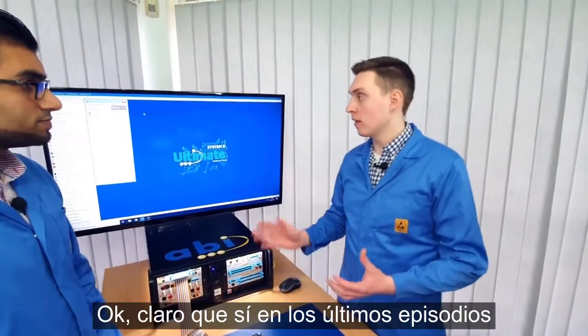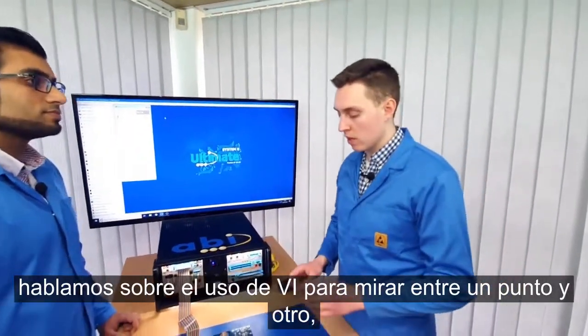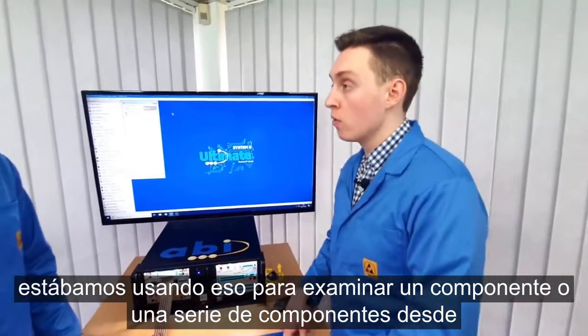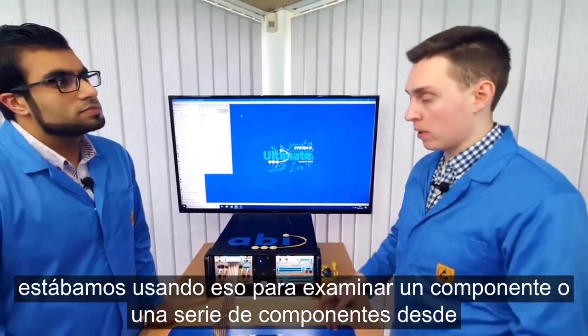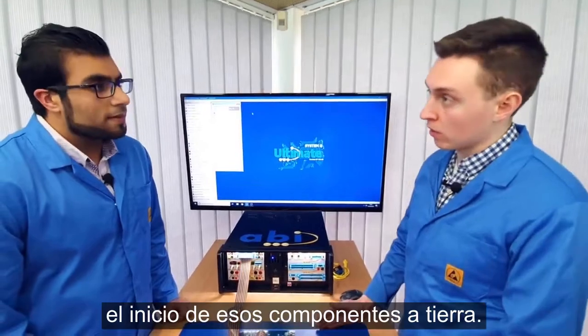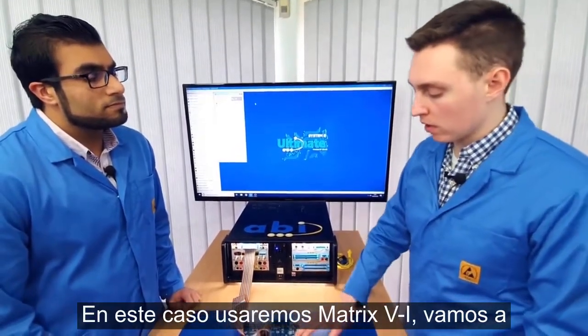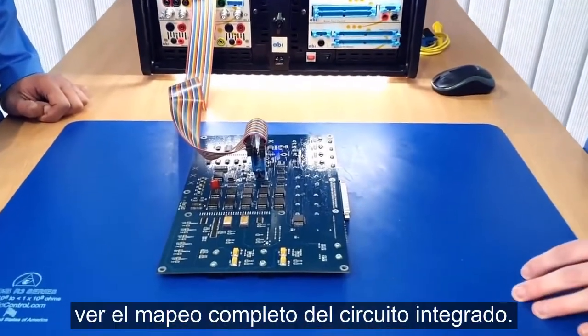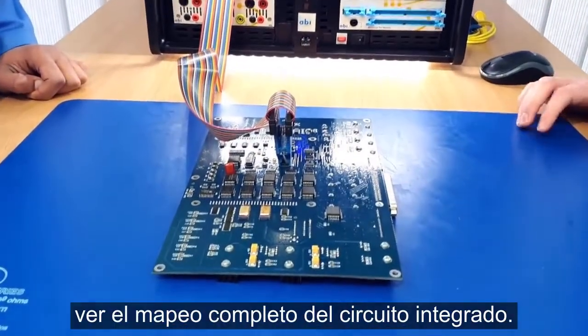Okay, of course. So in the last episodes, we talked about using VI to look between one point and another. Usually we were using that to look either over a component or a series of components from the start of those components to the ground. In this case, we'll be using matrix VI, where we'll be looking at from each pin and using all the other pins as a reference, so we get to see the complete mapping of that IC.